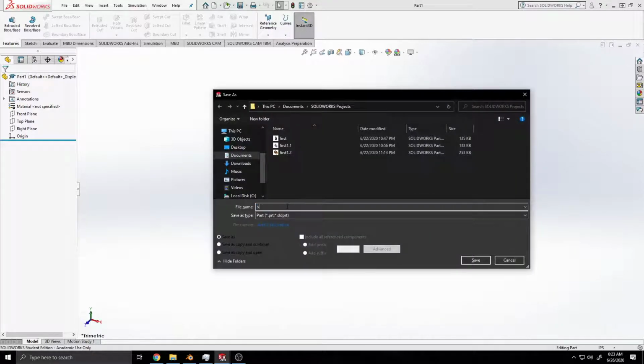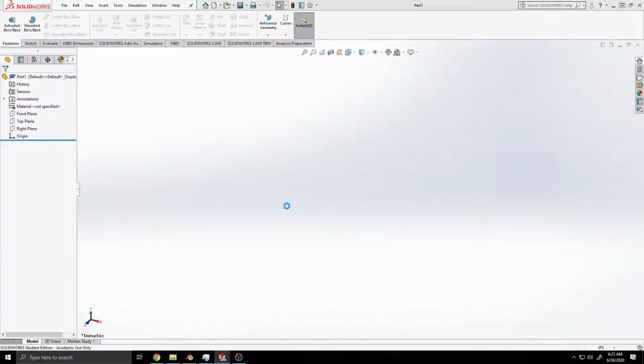Anyhow, the way we're going to model this is we're going to start off with just a simple revolve feature and this basic profile sketch that you see. It's going to revolve around this vertical center line, 360 degrees. You see, it kind of looks like an airplane almost, this profile. That's what we're going to draw.